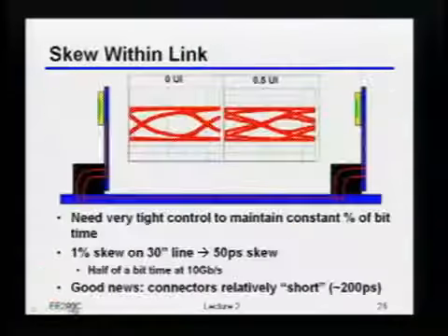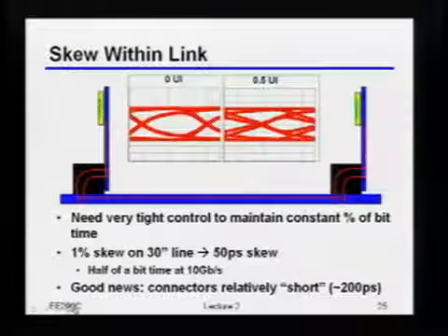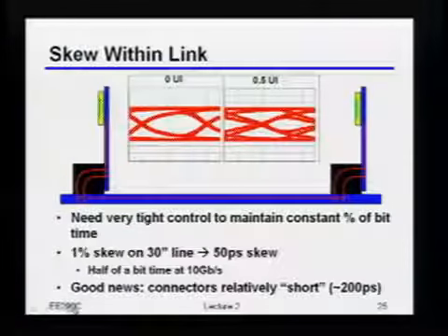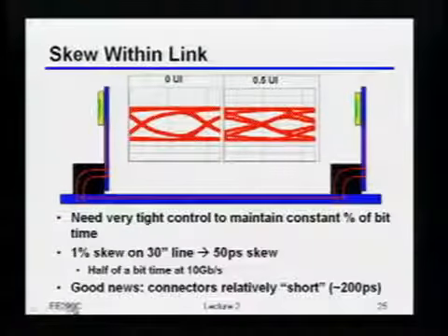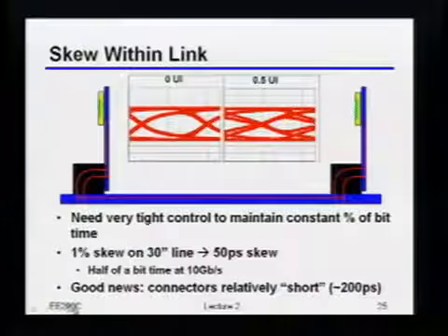The other thing I was actually going to mention right now is that you really do have to be very, very careful about differential wires in terms of routing them and keeping them balanced. Because, as you've said, you could think of it as, well, okay, if they're not balanced, they'll get really bad common mode immunity.